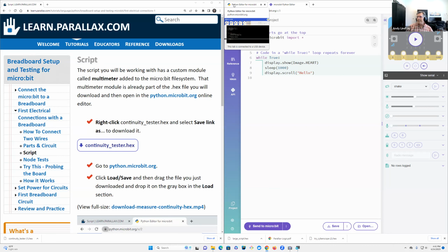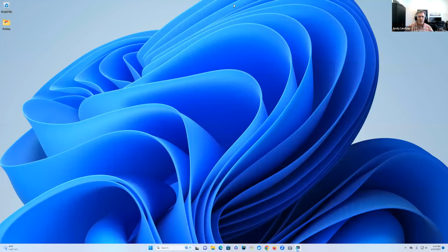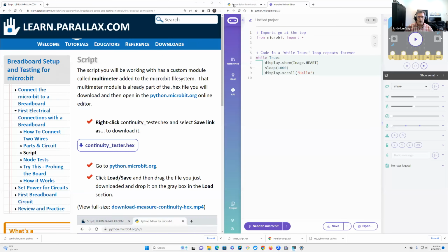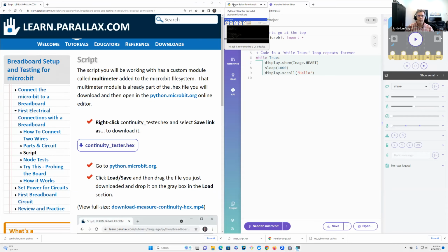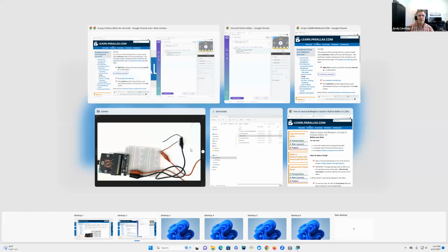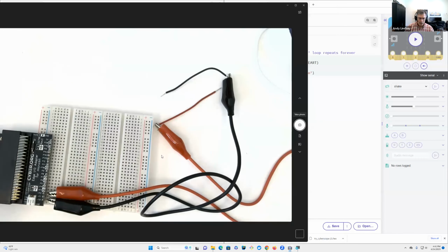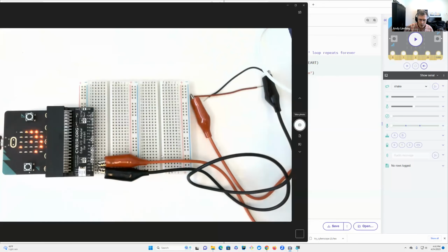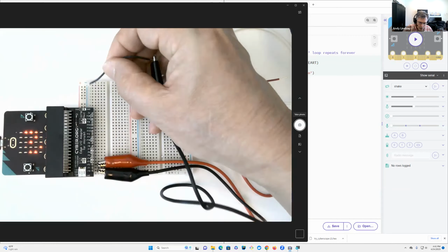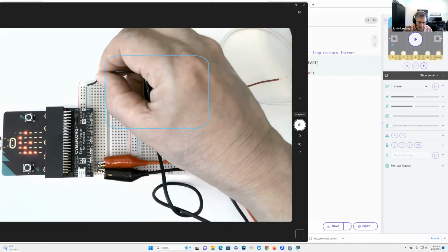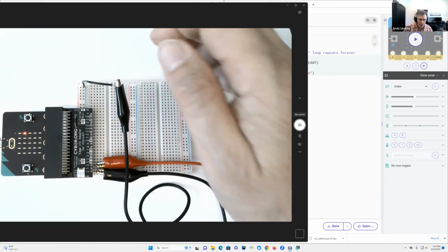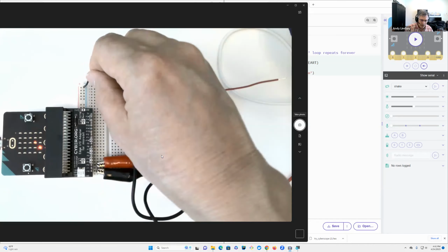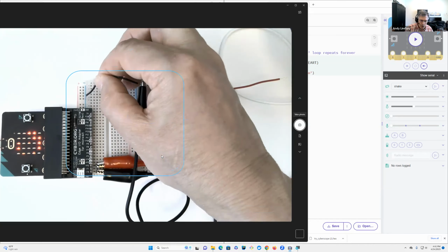Yeah, that'll do it. So that is something that a real continuity tester would not do for you. And I'm going to have to add that as a comment in the tutorial, that essentially when you take the ground lead of the continuity tester and plug it into this negative, this row is the negative terminal of the microbit supply here.